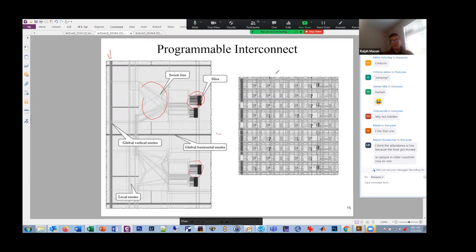And then each of these, there's a big massive array. So these global interconnects are running all the way down. And each one of those is one of these. And there's literally thousands and thousands of them. If you go into the Vivado software, you can actually see this view, and you can go in and look, and it'll show you where the interconnects are made. This is when you do the place and route, it's putting your logic into some of these blocks, and it's routing the connects, either local interconnects or global interconnects. So this is directly a screen capture from the Vivado software.